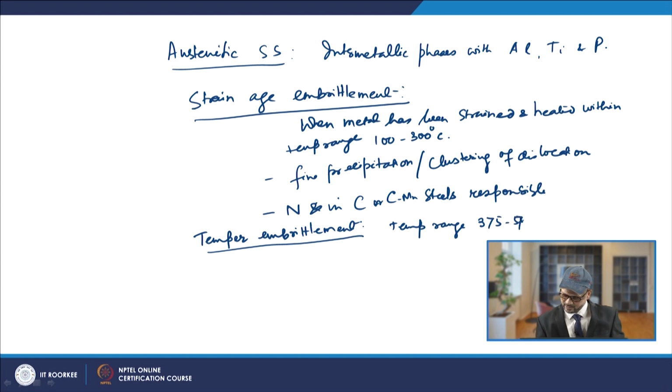So, this is 575 degrees centigrade. This is basically the tempering temperature range, as we all know. Once you do the tempering in this range, you have the formation of undesirable transformation products, and that is formed through grain boundary segregation, and that basically leads to a decrease in toughness, or an increase in embrittlement.